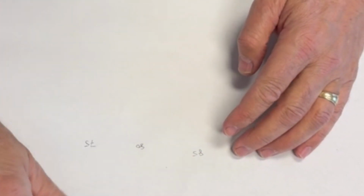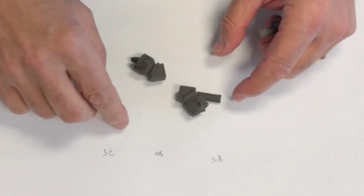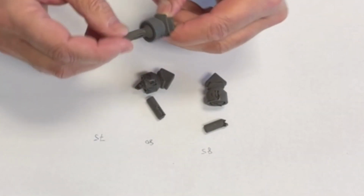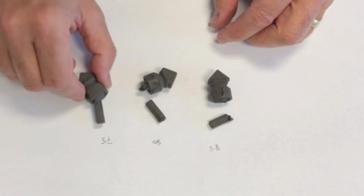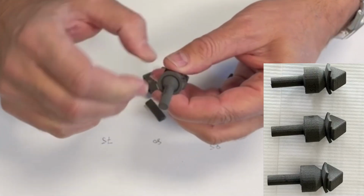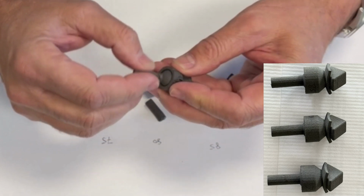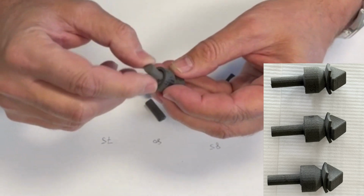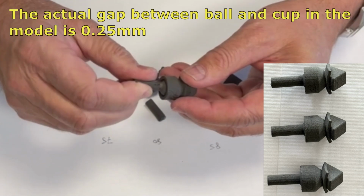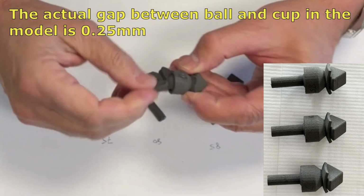And then the last, I wanted to do something that had a 0.3 millimeter tolerance. These parts are broken, and I'll tell you why. But this one's not, and this one moves, and it just so happens to be 0.75. It did take a little effort. I just had to put clamps on both of these and get it to work. And once it worked, it feels really loose in there. It has a 0.3 millimeter gap, and so it moves in there well.